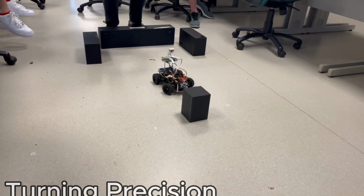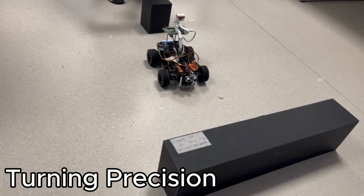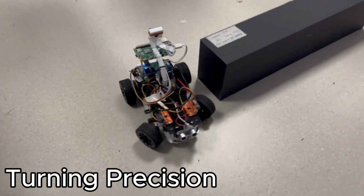To ensure our robot makes precise turns, we needed to make use of our gyroscope. We calibrated it by taking readings while the car is stationary and removed any offset and drifts. Once calibrated, the gyroscope's reading in angular velocity allows us to continuously track how much the car has turned, giving us a precise reading over its movements.